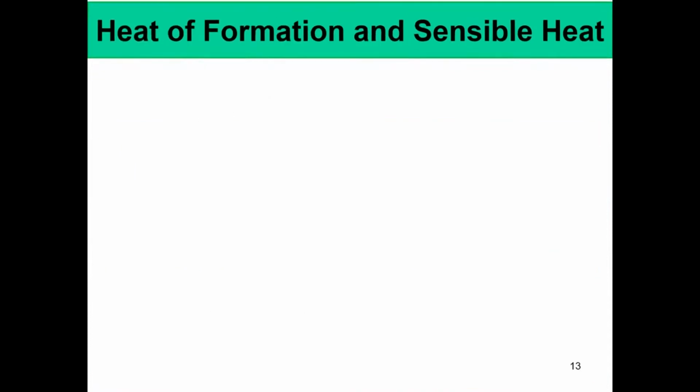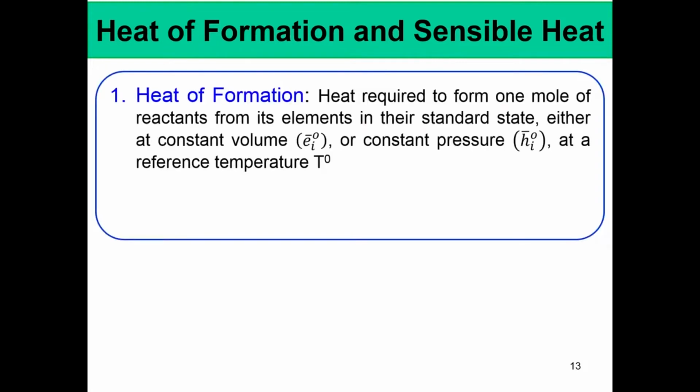But then the next important thing is how do you obtain the temperature, and for that we need to introduce a few concepts called heat of formation and sensible heat. The heat of formation is a very important concept. It is defined as the heat required to form 1 mole of reactants from its elements. Remember, reactants need not be elements; reactants are essentially molecules.